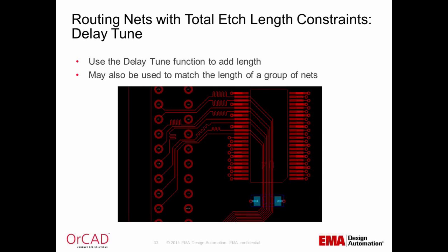The display constraint command reports the constraint value that was used to resolve the physical constraint on any single selected database object. It can also report the constraint value used to resolve the spacing between two selected objects. The display constraint command can help you see how the tool resolves to a specific DRC value.